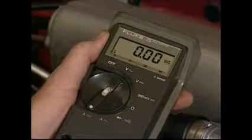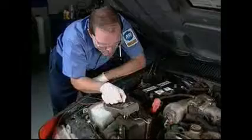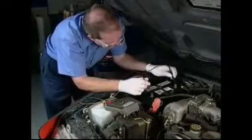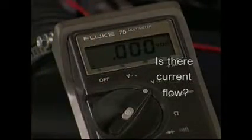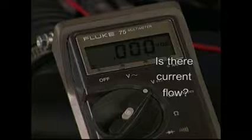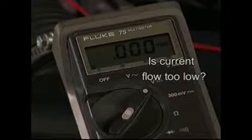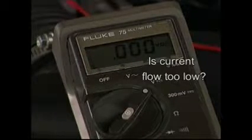The ammeter function of the digital multimeter is used to test for current flow. Current is measured in amps. Current is the flow of electrons through a conductor. Testing current will allow you to answer the questions, is there a current flow? For a circuit to work, it must be complete and current must be flowing through the circuit. Is the current flow too low? A low current flow is indicative of a high resistance in a circuit.